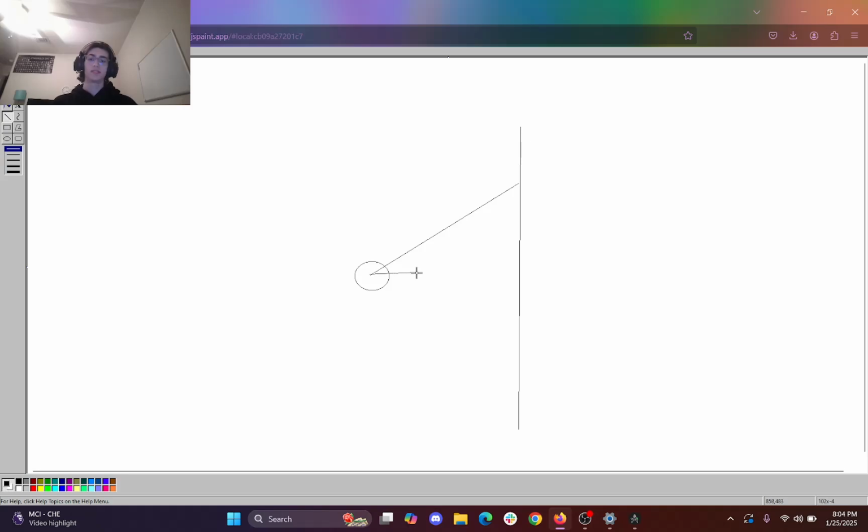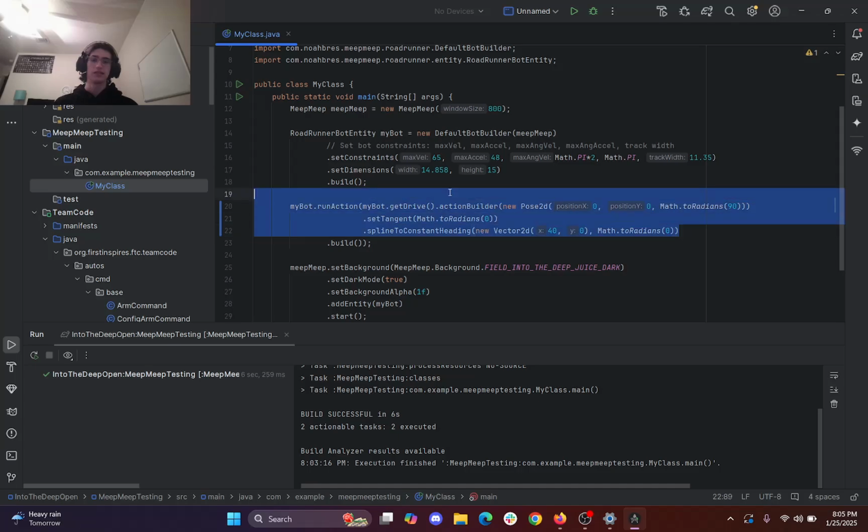When you do the line2 function, normally it will assume a tangent of 0 degrees, which means you will travel at a 0-degree angle until you hit the point. As you feed different tangent angles into the line function, you can change the angle in which you approach that coordinate. There are some limitations to this though. For example, you can't put in an angle of 90 degrees, or anything that would travel the opposite direction of the x-coordinate you're trying to reach, because then you would never complete the line and Roadrunner will throw you an error.